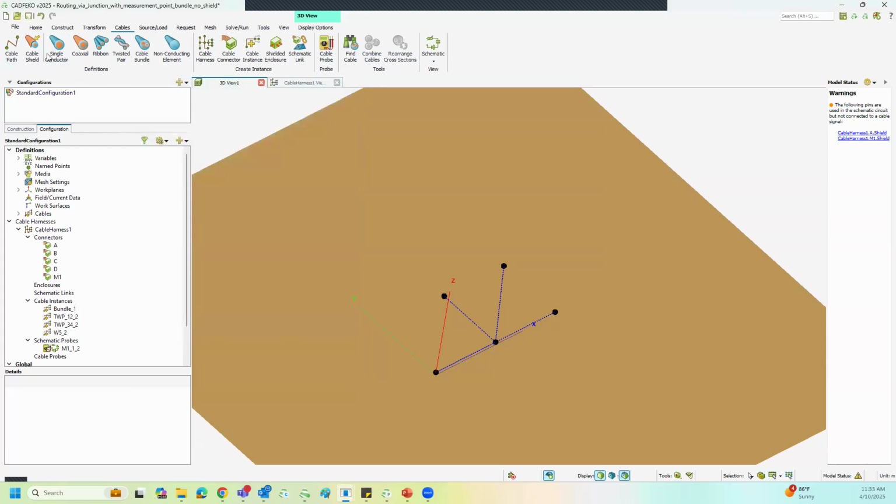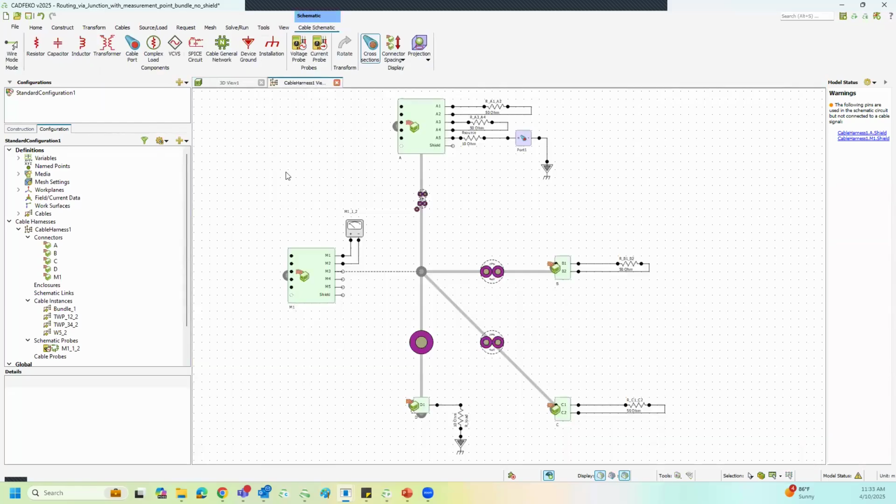Not only having all these options for different cables, bundles, and shields, once you set up a cable analysis problem in Feko, you can typically add different types of terminations on the cable terminals in the cable schematic. So you can see here, you can terminate the cables with different RLC loads, complex impedances, transformers, or voltage-controlled voltage sources.